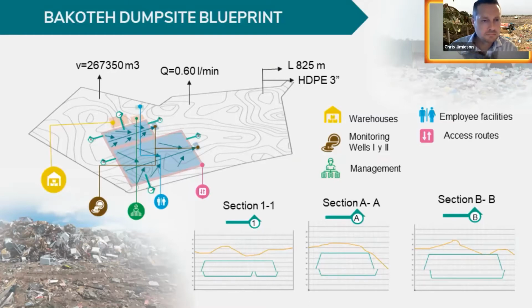For the beginning, excavations should be done down to the ground level, depending on the location of platforms as indicated in the report. After that, the next activity is to start to compact the waste until it reaches the appropriate level. In these images, you can see the profile that will be obtained after compaction. Later, the top cover is necessary. For the top cover type, the recommendation is to use the evapotranspiration cover, and it will have an approximate height of 1.5 meters, and we can see the structure in these images.